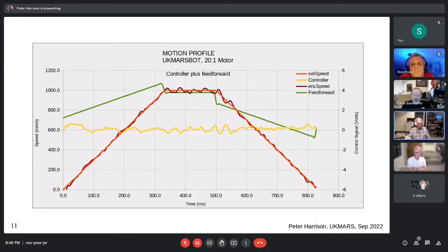That's why I go through this rather than just say, I changed a parameter and ran the mouse, look how much better it is. I could do that with the steering, but not with this. And when people respond by changing the KD term or the KP term, they'll do that, but you have to make quite gross changes before you can physically see a difference. By then, your controller's probably shot.